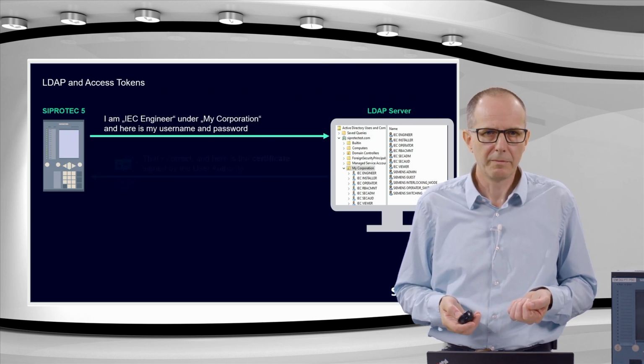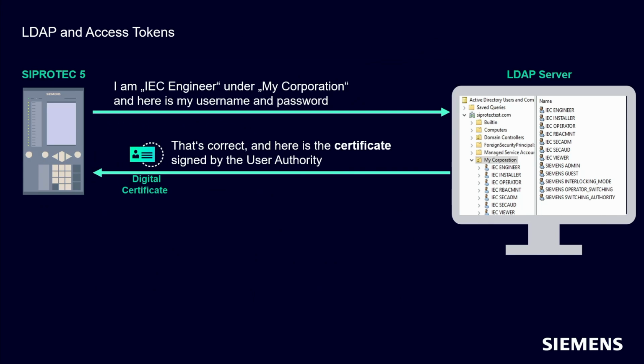After a successful binding operation, the client queries for the role information that the device needs. The second step is receiving role information. It is a little bit different from normal IT world practice, and the mechanism is fully specified in IEC 62351. To fetch the role information of a user, the client first fetches the user certificate attribute of the user. In this particular property of the user, there should be a binary certificate where the user role details are encoded.